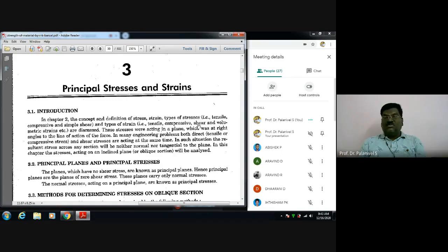Once you know how to compute this, moreover, for the determination of those stresses in any oblique plane, in an analytical way, we develop some expressions. They are called transformation equations. They transform the stress value to some other plane. That is why they are called transformation equations. We are going to get them for several cases. And next I am going to discuss the resulting strain, right?